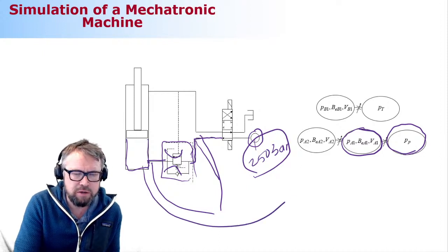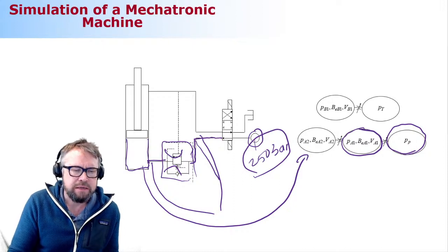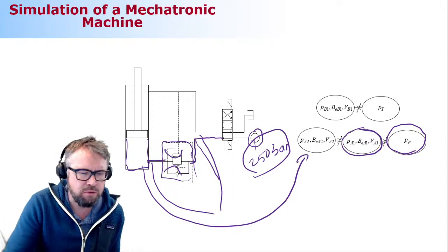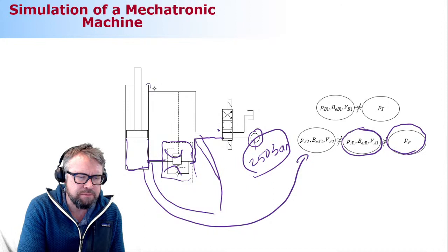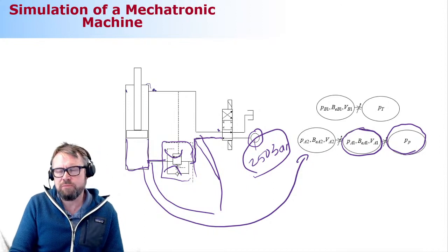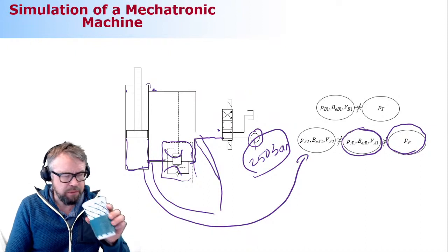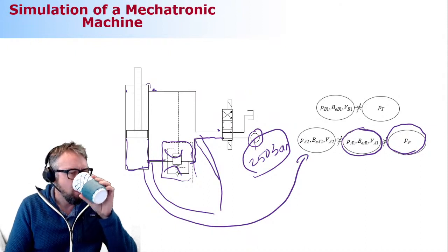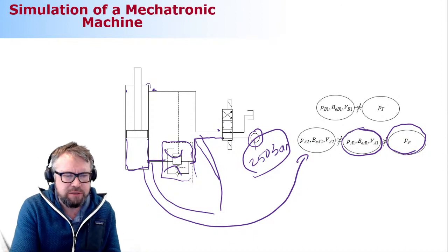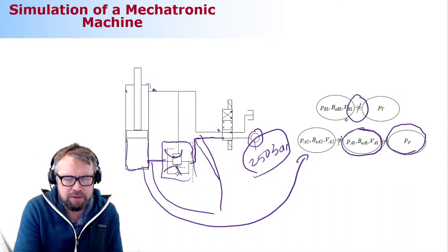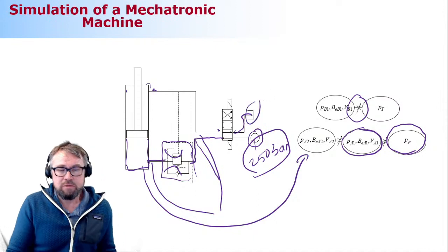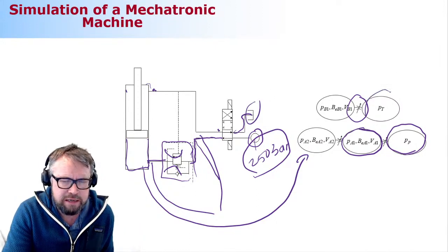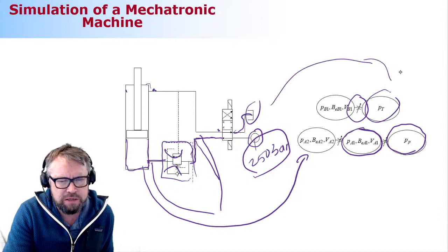And now this one here is computed by using this pressure here. Then on the way back, from the piston rod side, again I have this volume, and I'm assuming that the pressure here, here, and here is equal. So they're equally distributed. That's why the pressure waves I cannot take into account. Then I have this direction valve, which again is modeled by using a simple throttle, which is a function of, or can change, its size. And then this one here is a tank. So this is it. Really the tank is another thing where I'm assuming a constant pressure, let's say 2 bars.